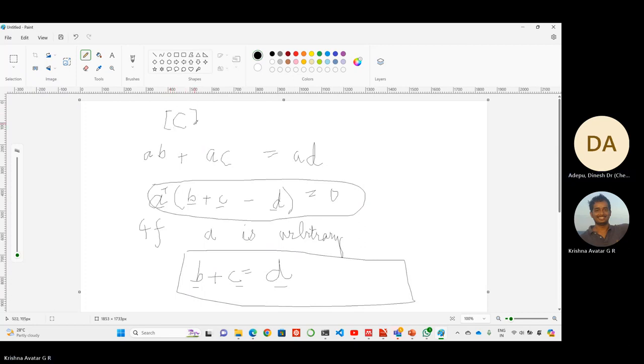Rayleigh came up with this just to exploit symmetry, because we don't have a perfect representation of damping. It is just for exploiting the properties of matrices. Symmetric matrices have a lot of properties, isn't it? Eigenvalues are real and eigenvectors are orthogonal. So those properties are very useful. So this is what is known as Rayleigh damping.